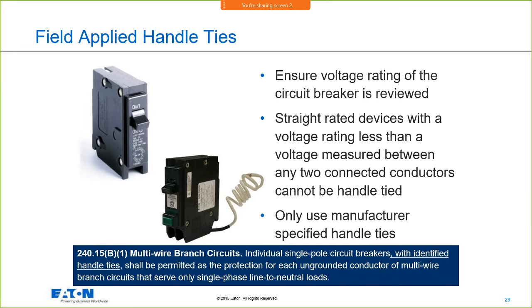And so if you have a standard thermal mag breaker, most of those standard thermomagnetic breakers will have a slash rating. You'll notice on this breaker right here, do you see the label right there? It says classified product. That doesn't mean it's top secret. That doesn't mean that you're going to have to erase your hard drives now that you've seen this product. That just means that you can put that product into other manufacturers' panel boards as long as you follow the instructions and only put it in the panel boards that are listed there.